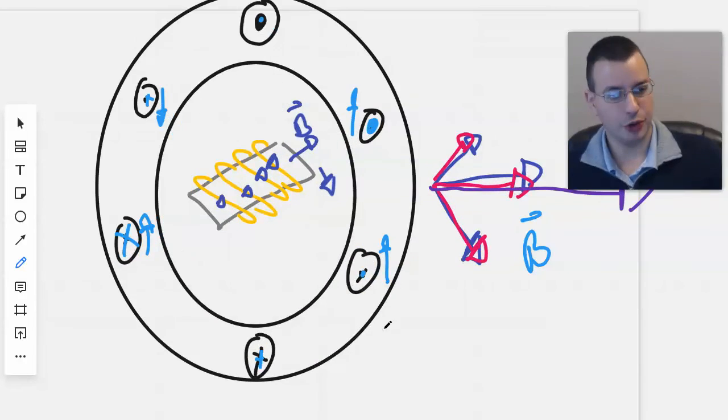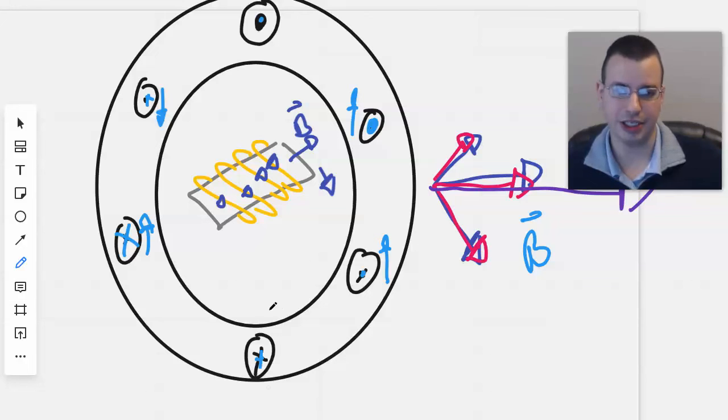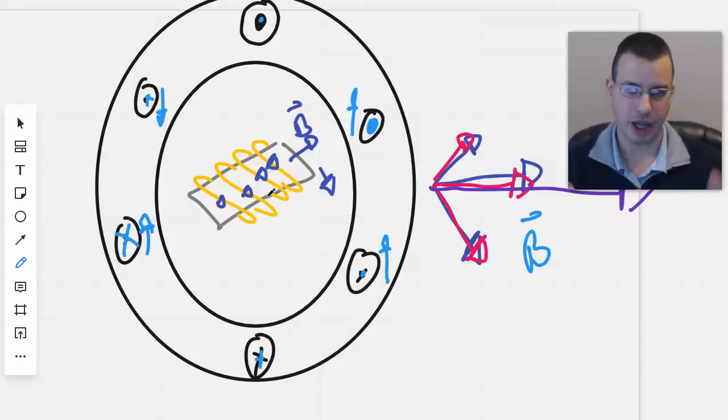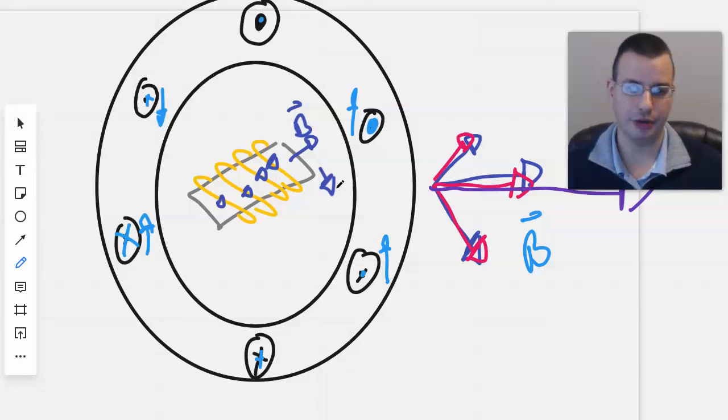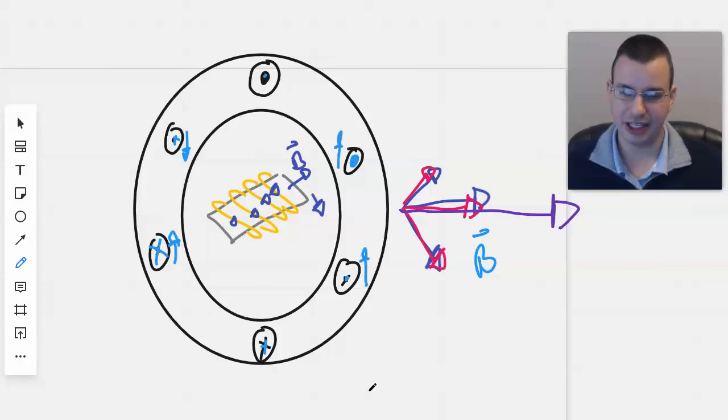And then we talk about field windings and armature windings. So you have stator on the outside, rotor on the inside. These are the field windings on the inside because the entire purpose of this magnetic field is just to create a magnet, which is then pulled around, and the armature windings would be on the outside. And that's the idea of an AC synchronous motor. Lots of different ways of engineering it and engineering details that go into it, the nuance, but that's the general idea.